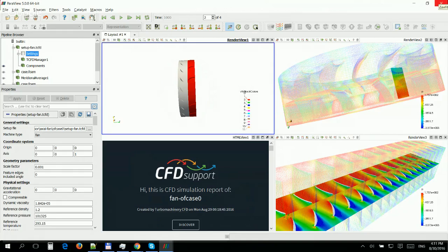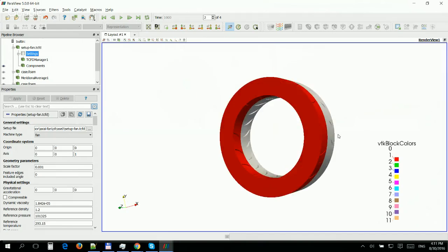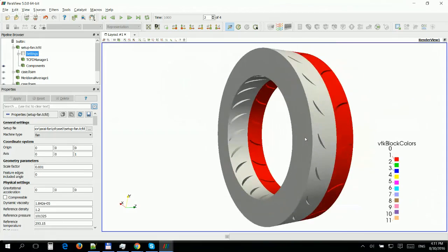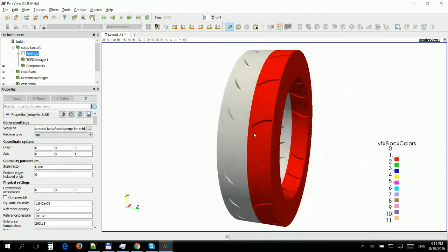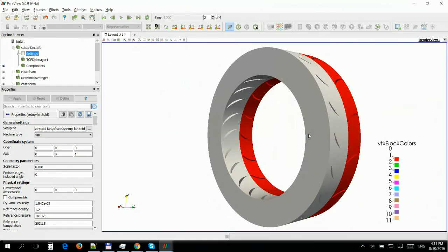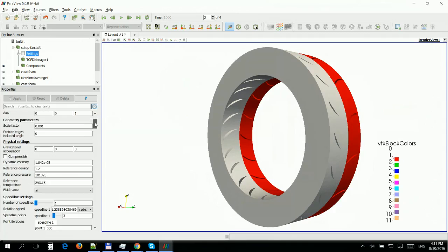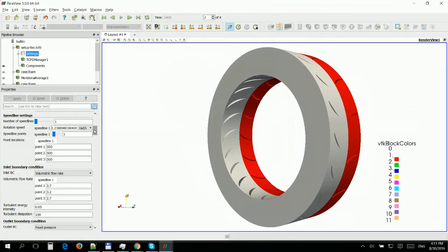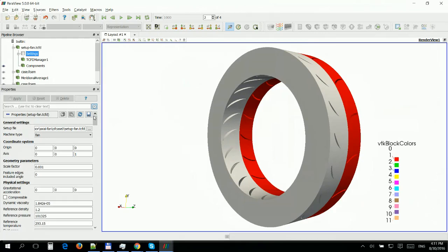Each Turbomachinery CFD simulation has its inputs, and those inputs are the surface geometry, which is a 3D model that creates the machine we want to simulate, and also the settings, which are the physics, boundary conditions, speed of rotation, and constants and settings of the solver. All these configuration settings are written in the configuration file.